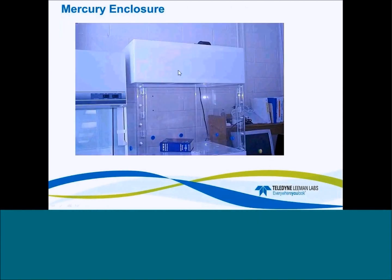So many people use an enclosure. This is one that we happen to offer. It has an adjustable flow fan with a HEPA filter, and you keep a positive pressure inside the enclosure to prevent any mercury that may be floating in the air attached to dust particles from getting into the system, into your samples.